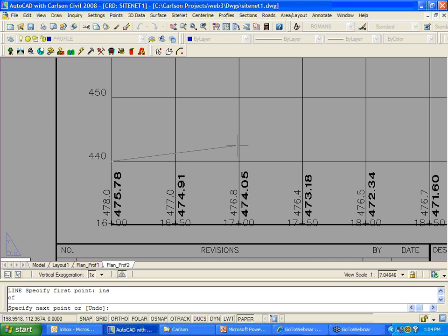So I guess to be specific, and this is something else now. Actually, I never thought of this, but it's something else. In that drawing, Profile 6, Profile 7, or whatever yours is called, it's not so much 0,0 as it is the base point. BASE. You type that word base. That, I believe, is what it's keying to. I need to do a few experiments to test that, but that's what you want to play back and forth to discover.